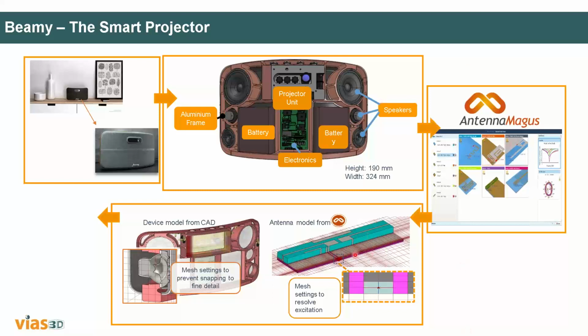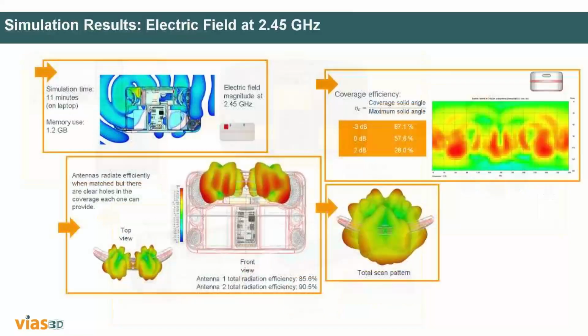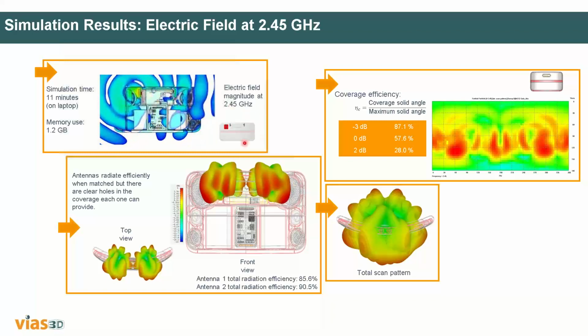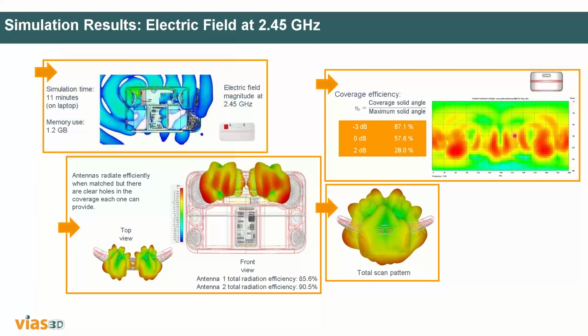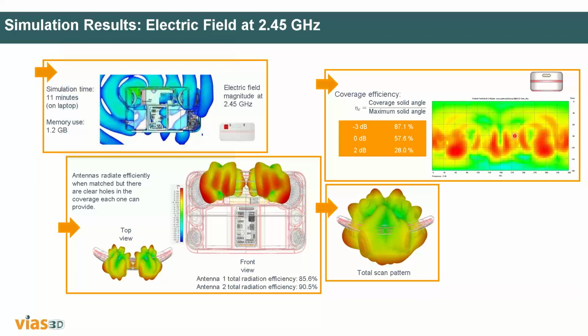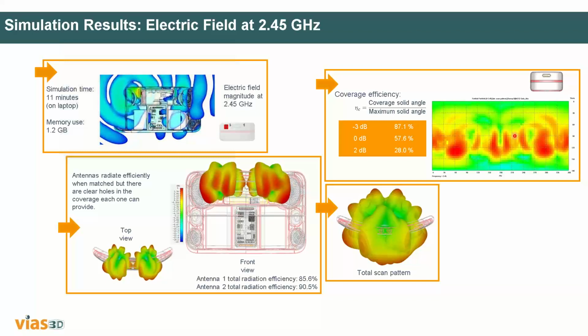And if you select a particular antenna and place it over here, you will get your resultant pattern. You will get the near field pattern, which is also important. You get the far field pattern, you can combine the patterns together, and you can also see the coverage efficiency of the particular antenna. After doing all the studies, you go for your certification, especially when you are designing something for a product. The product has to get certified by the relevant agencies, and only then can you go for mass production. So that is one of the important things.